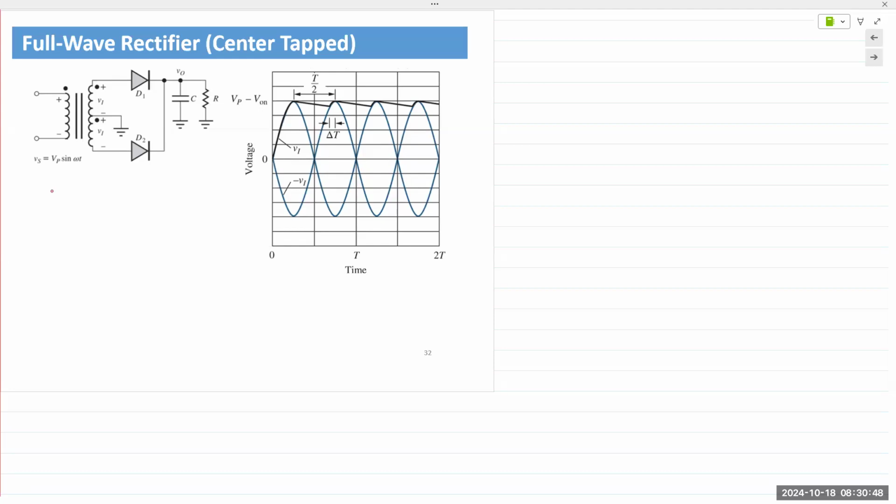Tapping simply meant you have a primary coil and a secondary coil, and all you're doing is somewhere in the middle of the coil, you're taking an output. You're tapping into it. So it's basically as if you have multiple secondary windings. It actually is wound around the same core. You're simply pulling an extension out, you're pulling a contact out. That's the simplest way to look at it.